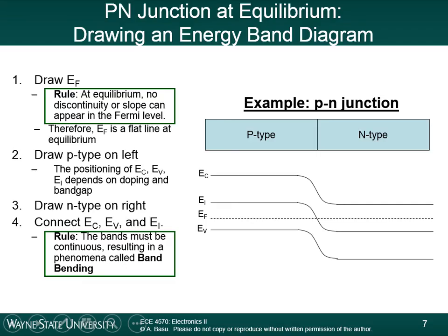and it'll move down here. Now, what this means in the valence band, we're not really concerned with electrons because most of the band is full. What we are concerned with is the empty states, the holes. So a hole, interestingly, will actually move up the slope, okay? Because as electrons move down the slope, if there's a hole here, for example, let me draw this out.